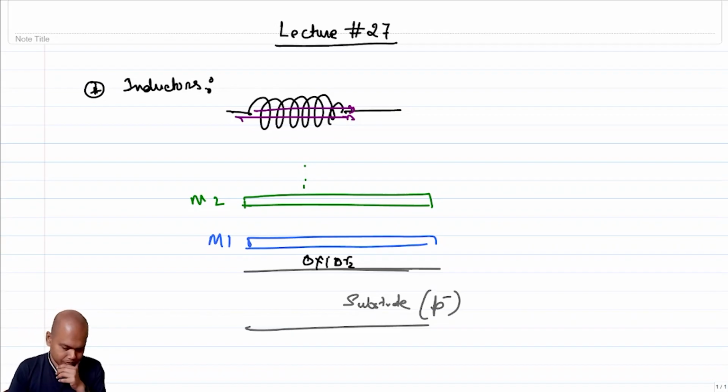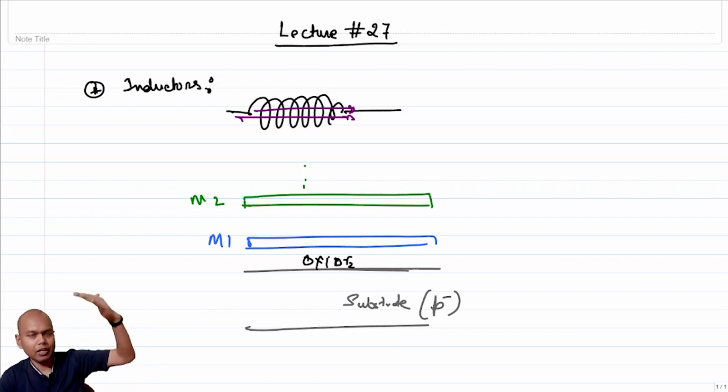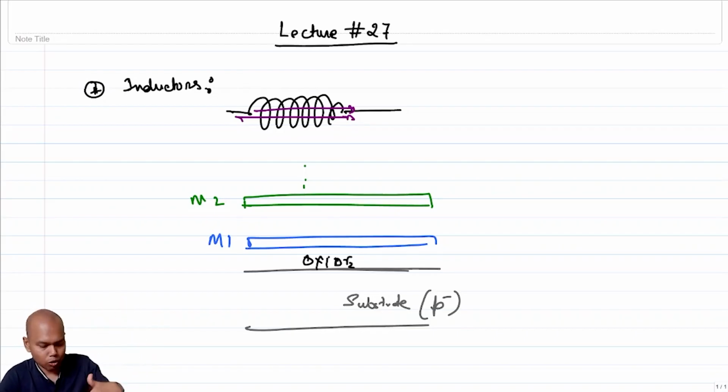So now, let's assume you would want to make an inductor. How do you go about making an inductor? You can think that your IC design is essentially a planar topology. Even though you have multiple layers of metals, if you have to go from one metal to another, you'll have to connect them via vias, which are essentially tunnels from one level to another.